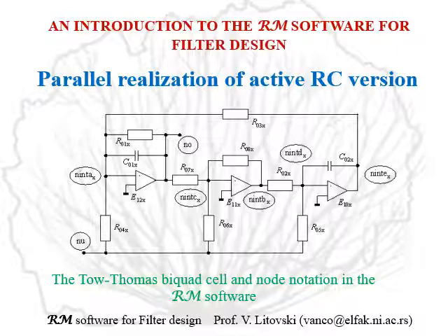It is really simple. So there is a first order cell, and there is a second order cell with two variants, of high quality factor of the pole and low quality factor of the pole. Altogether 3 cells, and that's the summing amplifier.